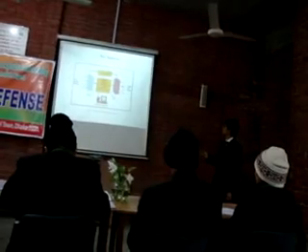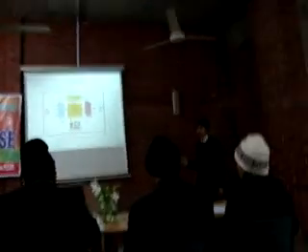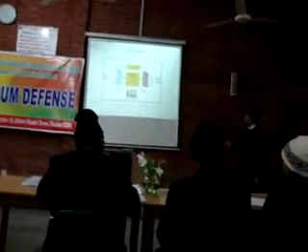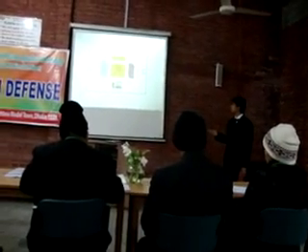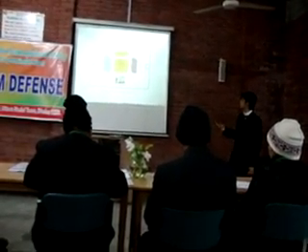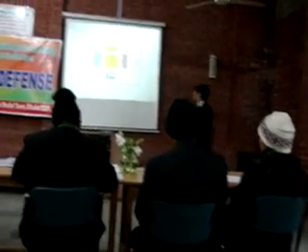This is the small PLC system. In a larger PLC system, the power supply section will be different for different types of input modules. And this one is small, so that is why the power supply is the same for the CPU and modules.